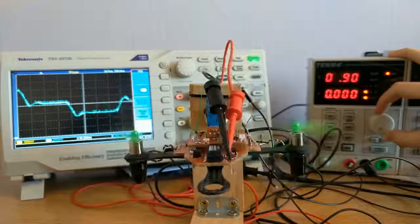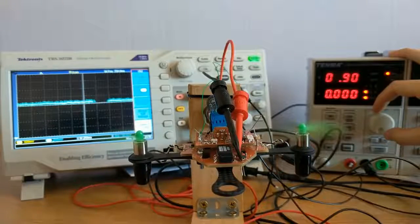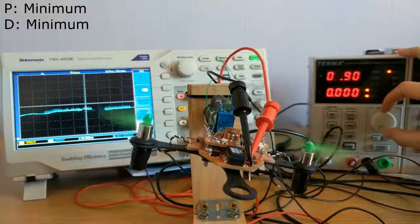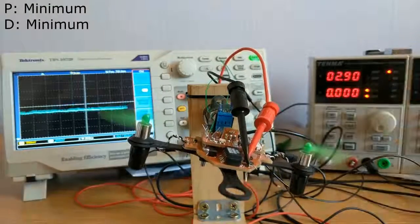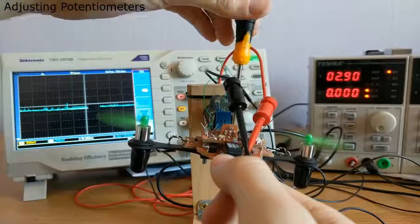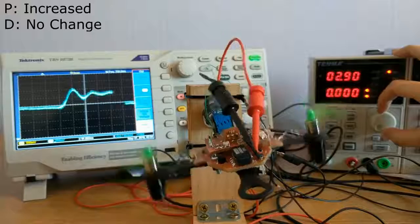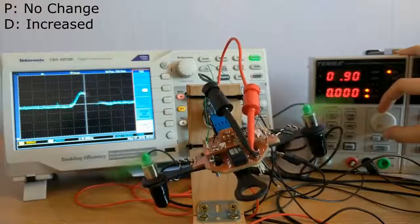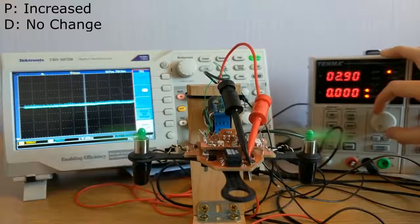I can use the power supply to generate a step input and measure the output of the inertial measurement unit to judge the step response of the control board. I can use what's seen on the oscilloscope to tune the PID system. My tactic here is to increase P gain until the system overshoots slightly, and then increase D gain to compensate, and then keep cycling. More P.